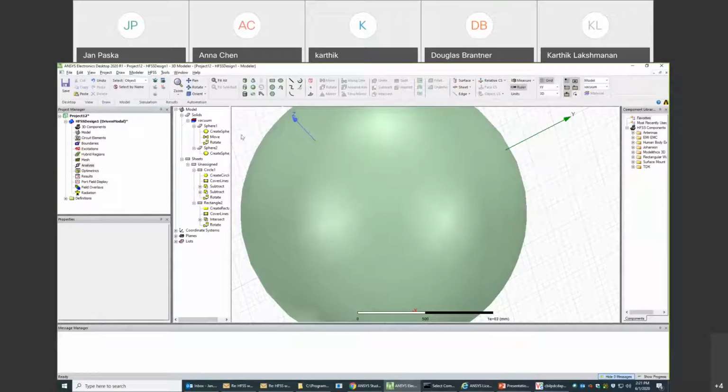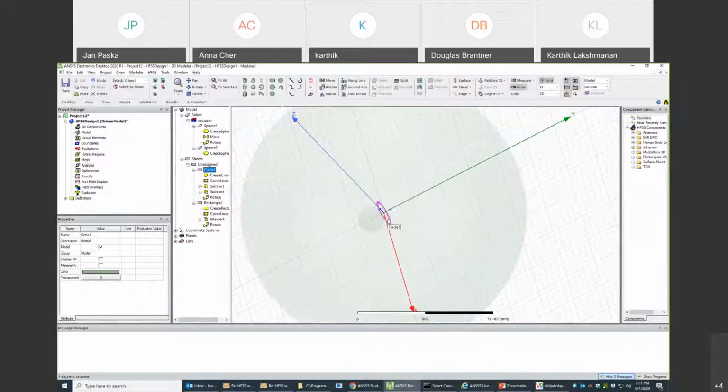And the distance to the antenna should be wavelength over 4. And at 3 Tesla, the wavelength is approximately, let's say, 3 meters. So lambda over 4 would be 3 over 4 meters. Let's approximate it to 1 meter. So the numerical domain needs to be 1 meter away from the radiating element.